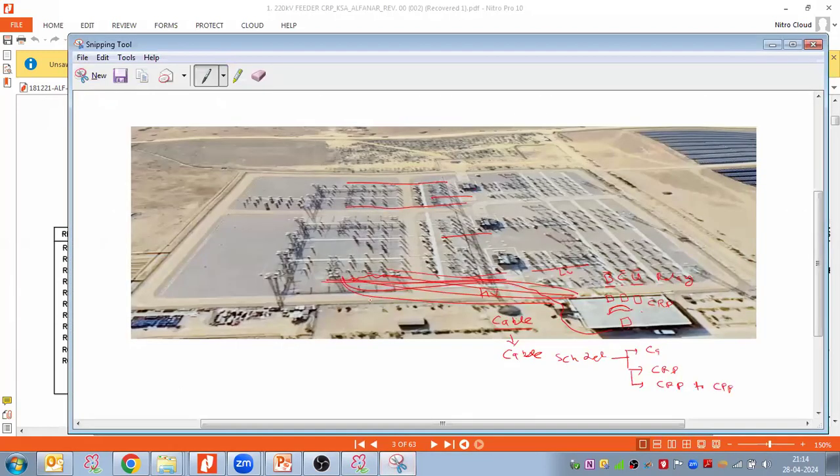So what we are doing is that in each and every bay, near the circuit breaker, we take one marshalling kiosk, the BMK box, which is called the bay marshalling kiosk. Instead of taking cables from all equipment, isolators and others, to the control room building, we take all the cables from equipment to the bay marshalling kiosk, and from the bay marshalling kiosk we can take multi-core cables, like 2, 3, 4 cables, and connect them to the control relay panels.